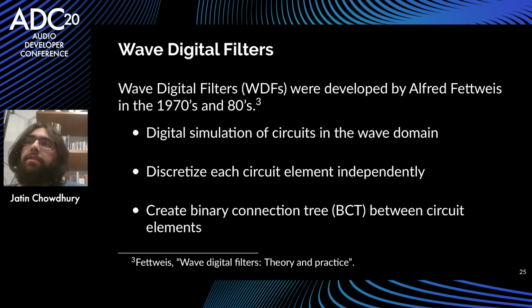So with nodal analysis, we had to look at the entire circuit and then discretize the entire circuit at once. In wave digital filters, you look at each element, the resistor, the capacitor, the inductor, and so on, and you discretize each element by itself, and then you can connect those elements in the wave domain, or in the digital domain, sorry. So this is really convenient because it allows us to swap out resistors and capacitors and so on in the digital domain, and we don't really have to care about how the wave digital filter reacts, because we know that it'll handle everything correctly so long as the conditions that I've mentioned are satisfied.